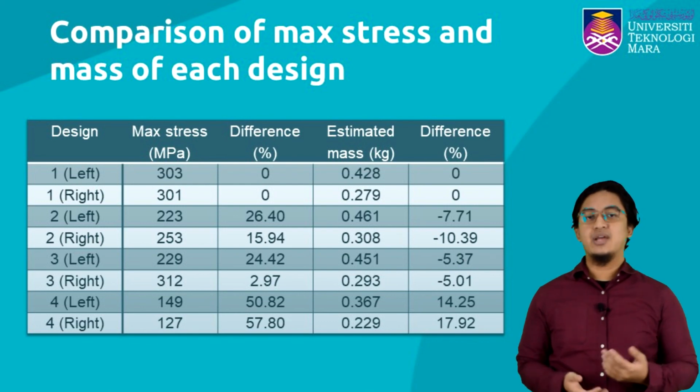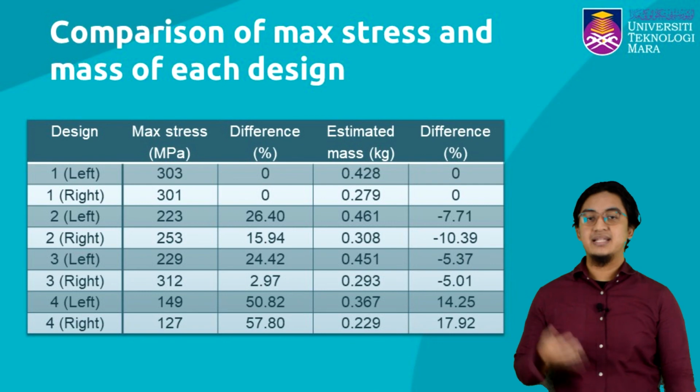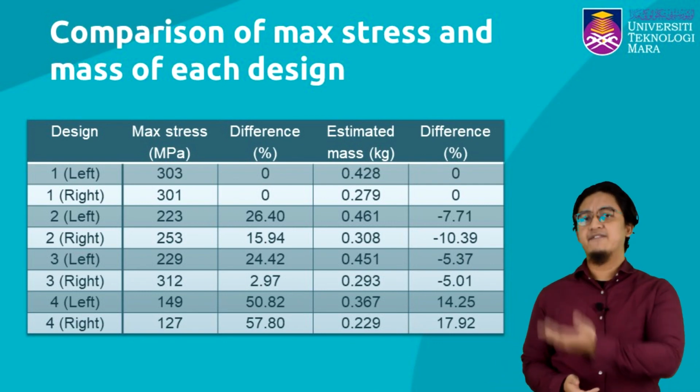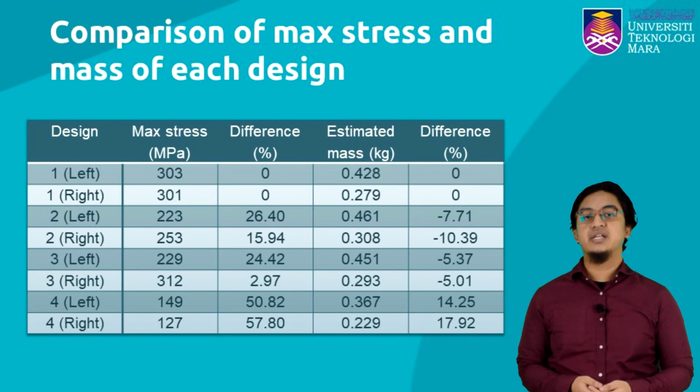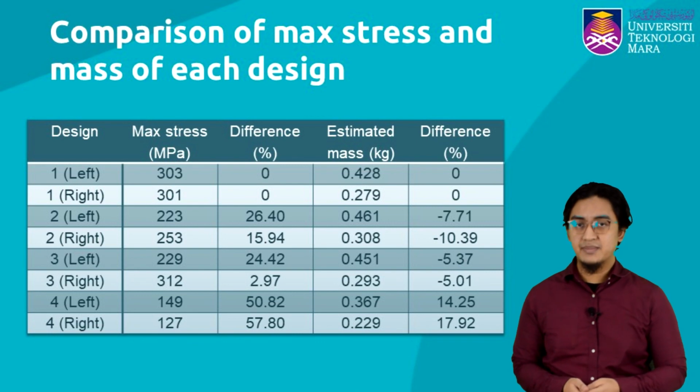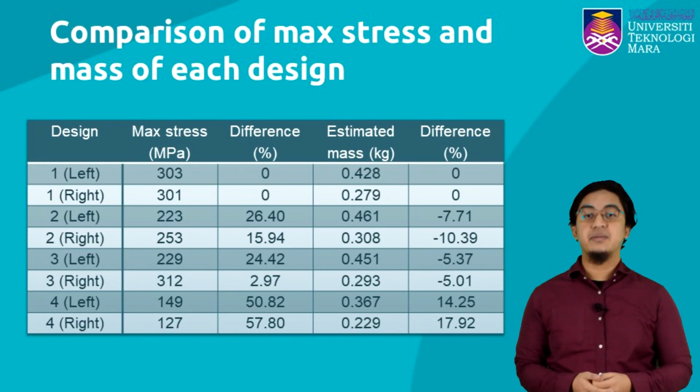I chose design 1 as the datum because it is the original design of the mounting. As we can see, design 4 offers the most reduction in maximum stress, which is 57.8%. However, design 3 shows the least efficient design, where the maximum stress is increased by 2.79%.